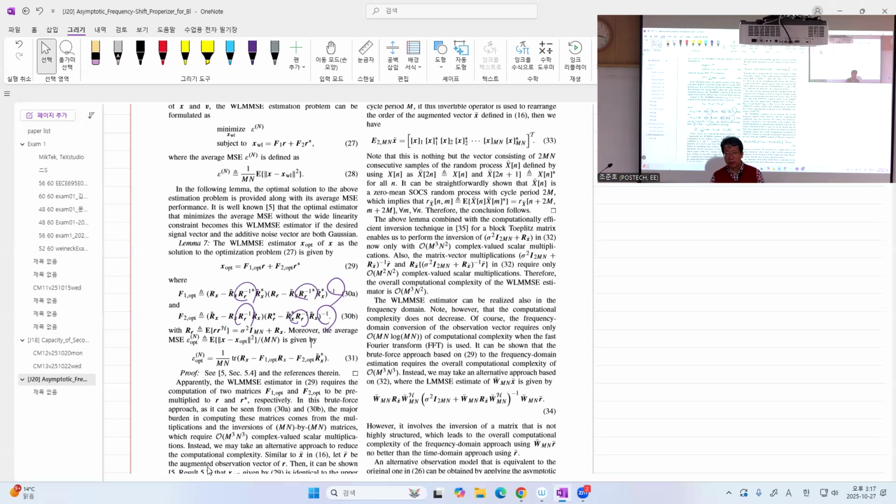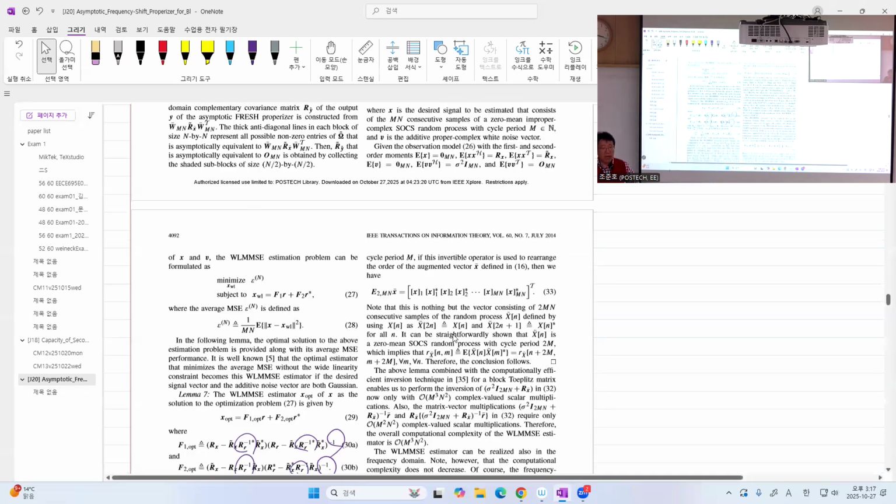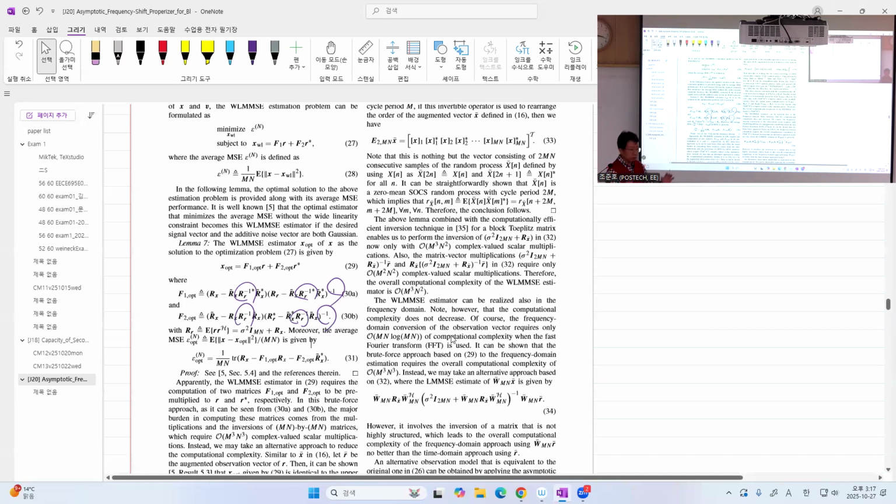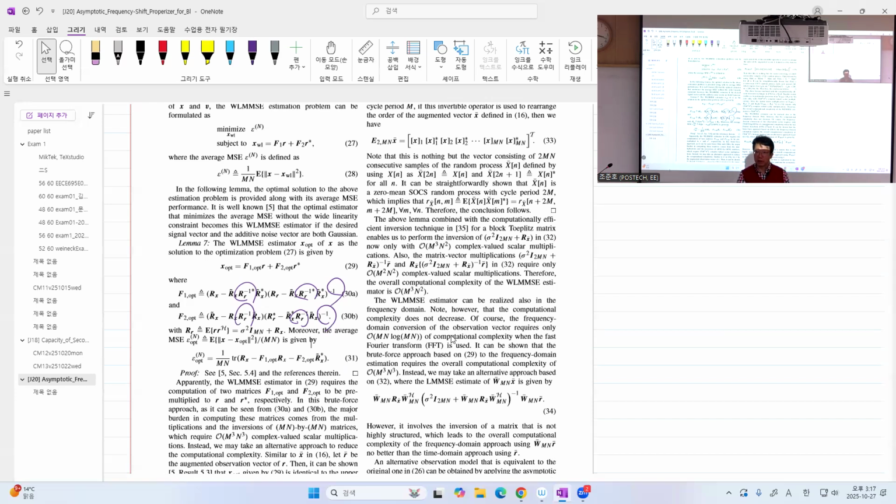And the interesting thing is that this paper shows that if we have cyclostationarity of the discrete time signal from which our vector is taken, then we don't need this augmentation. We just need to immediately transform to the frequency domain, and just sub-block flipping and conjugation will give us all the information to process.